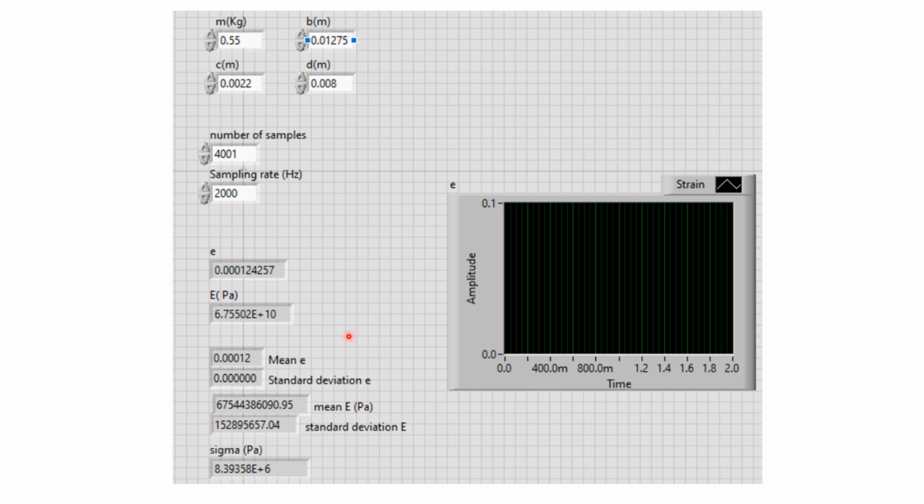After we have run the calibration and run this, we're going to look at these values just to see if they make sense. The dead giveaway is your mean E. So if you're looking at this and ask, does it make sense for that material to have a Young's modulus of elasticity of this value? You can compare it to other materials and ask, does it make sense for this material to have this E?